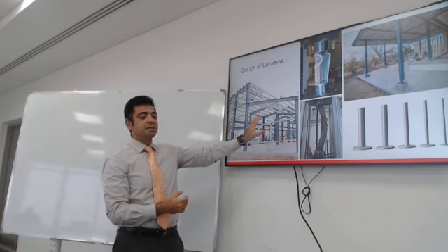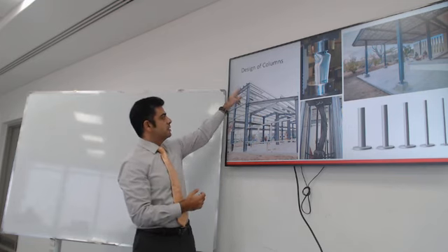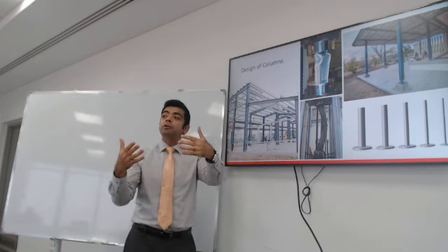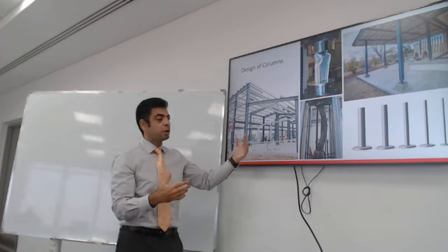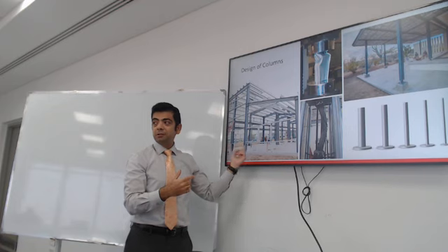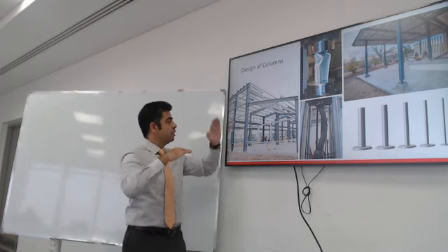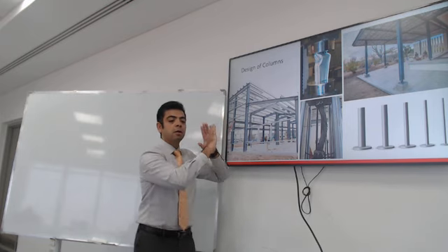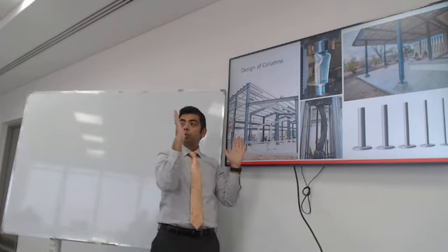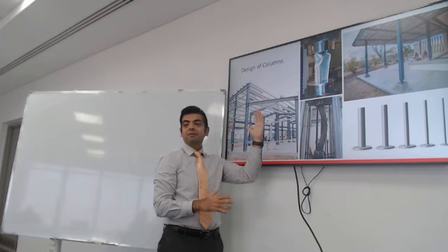If you look at this example, this is an exterior column, on the outside wall. It's still under construction, but these girts, these horizontal beams, will support walls or windows, and they will create a projected area for wind to pressurize the wall.